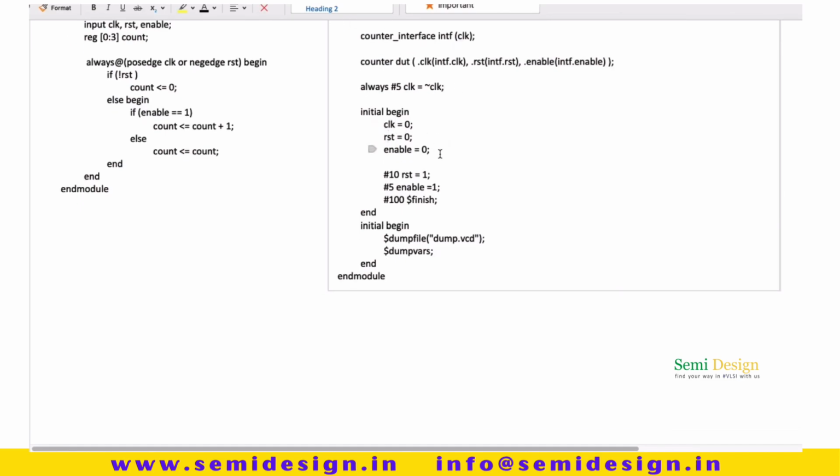Now we are initializing the signals. Clock is first 0. As reset and enable are declared under the interface, we use intf.rst and intf.enable.